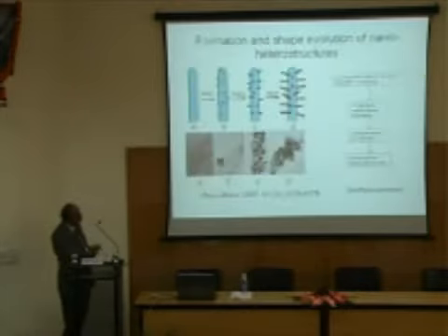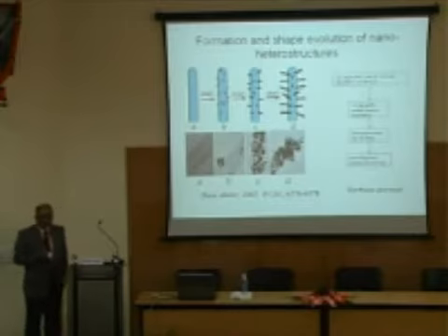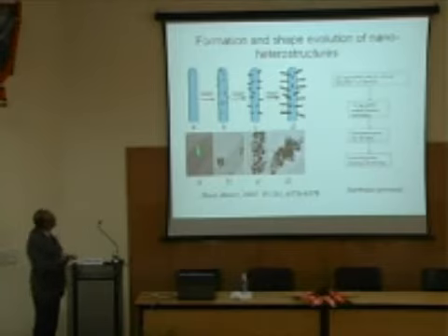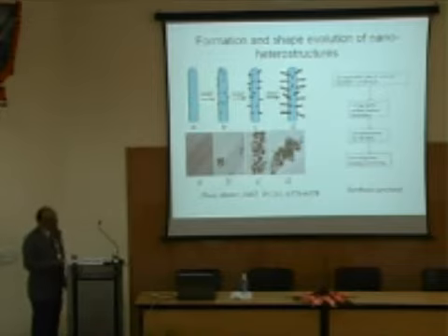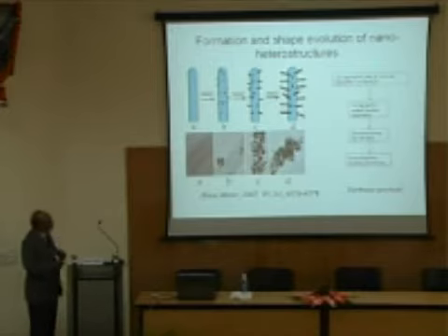Now, this is a technique by which you use a template to make a wire which can be conducting. You start with a template; the template can be a carbon nanotube, that is the simplest template you can choose. So, you have this carbon nanotube and then you do the chemistry on the carbon nanotube. You add all these liquids, they have a metal source, platinum, you can read Pt here. This is a solution called chloroplatinic acid, okay?